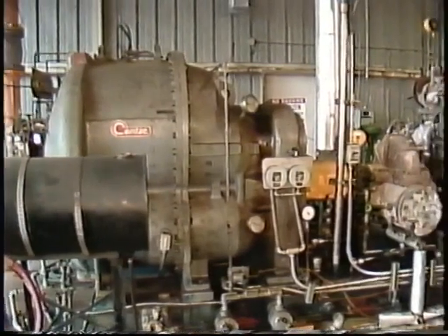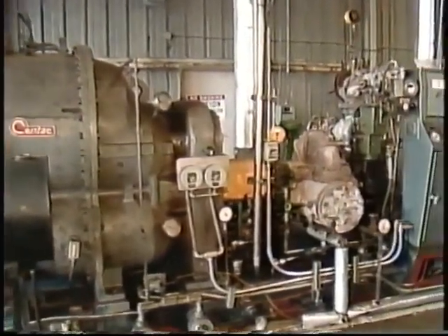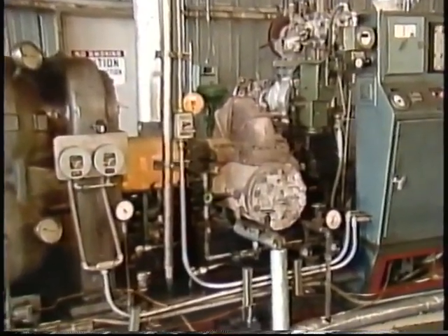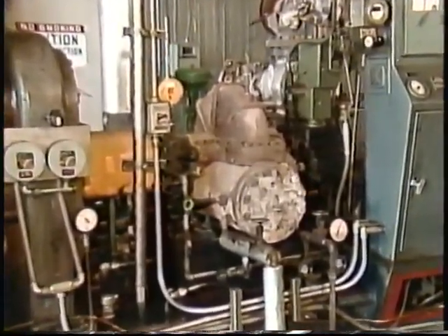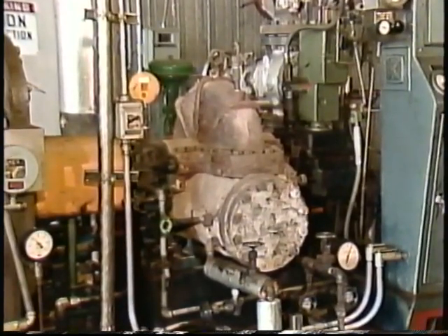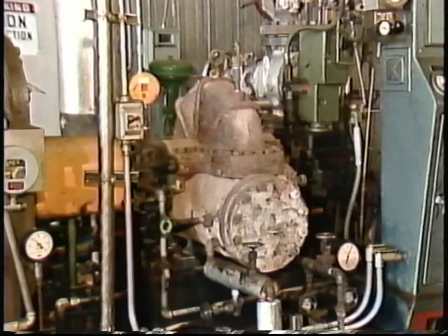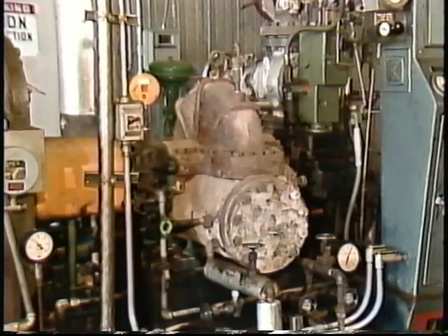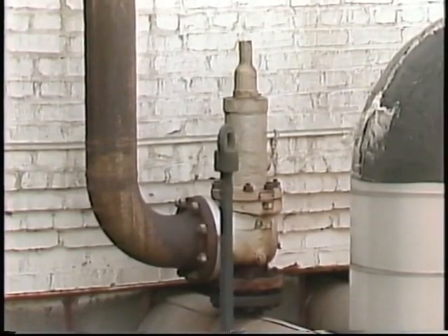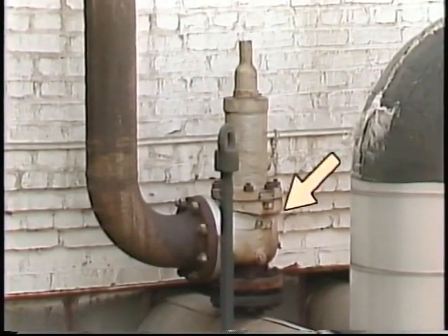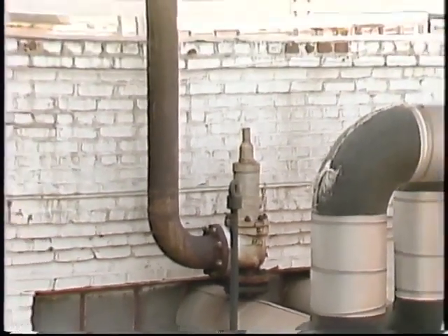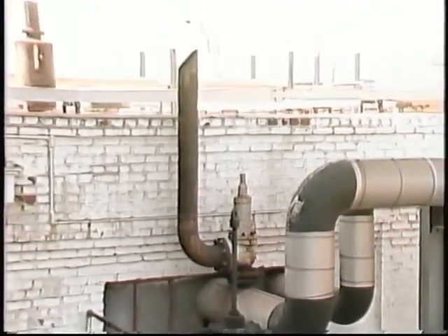High pressure is another factor that makes it necessary to use auxiliary valves. Generally, the turbine casing is designed to handle pressure within certain limits. If the pressure exceeds the design limits, a literally explosive situation could occur and the casing could be damaged or destroyed. To prevent such a catastrophe, most turbines have a safety relief valve. The safety relief valve for this turbine is located in the exhaust line.